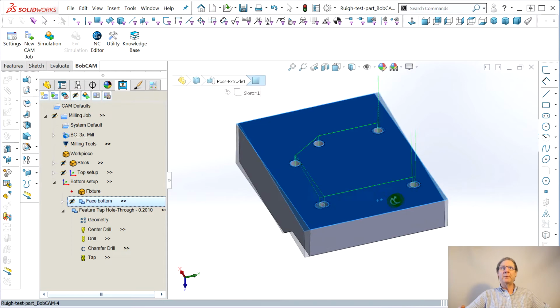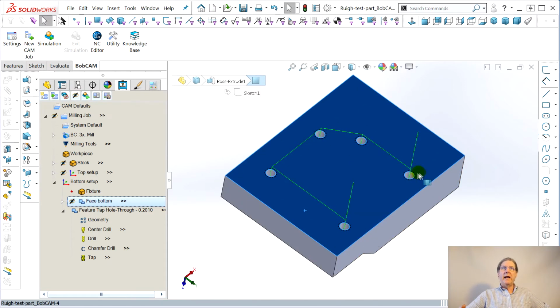It won't open in your paid-for version. And it's doing them in a sensible order. This is the problem I've had with all these programs. You let SolidWorks CAM by CamWorks do automatic feature recognition. Well, it wants to do 2 holes from the top, 3 holes from the bottom. When obviously, not artificial intelligence, but the average person would say, oh no, you do all 5, same depth, same everything. Even when I flipped it over, it still wanted to break it into 2 groups.